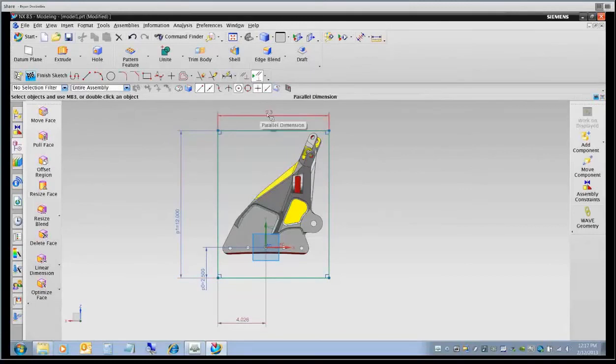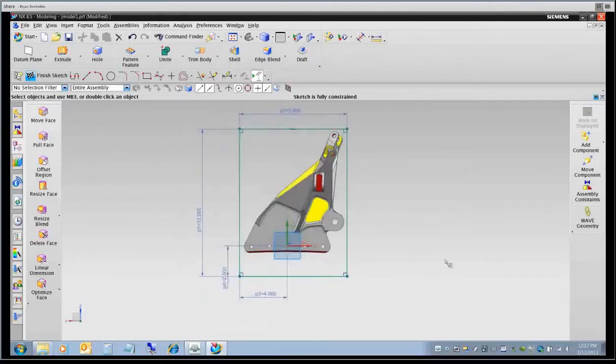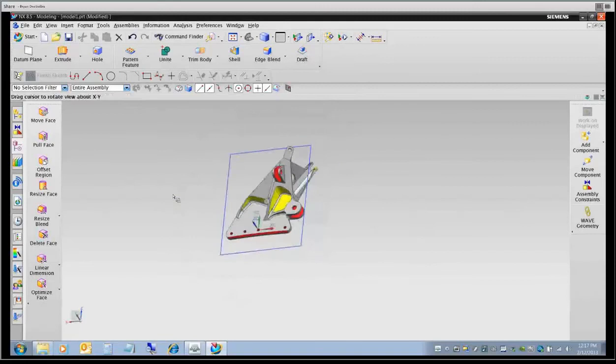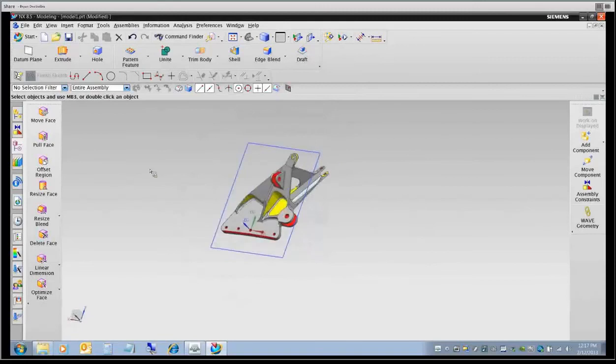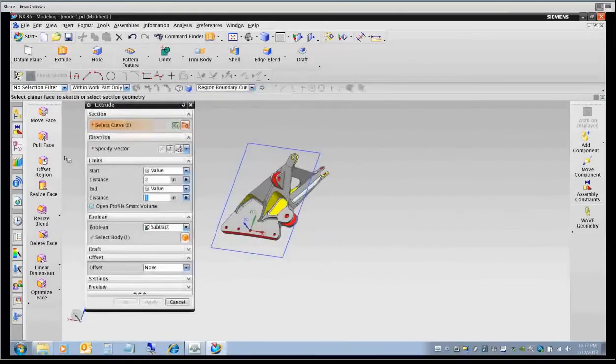So we were talking maybe about a saw cut type operation. Same thing maybe with our width of the part. Maybe we can make it a little bit smaller, and we can adjust our centering right and left from there. So maybe we'll make this number 4 inches. Maybe some people like that as more uniform numbers, and this would give us a start for a blank preparation, right? So with this, we would go ahead and create what that volume is that we would use for our stock boundaries, for working on our part in here.